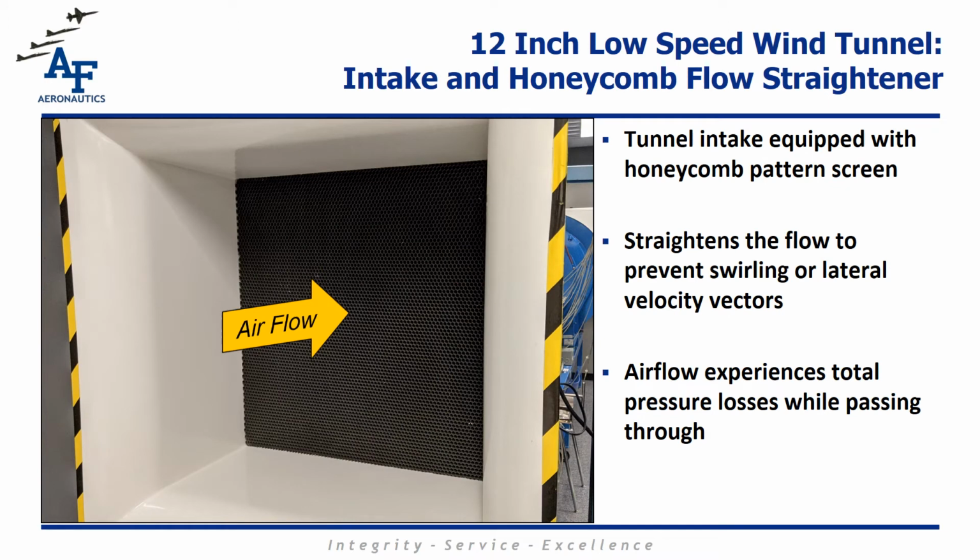The intake to the wind tunnel is equipped with a honeycomb flow straightener. This prevents any swirling effects as the flow enters the test section. The airflow also experiences pressure losses while passing through the honeycomb flow straightener.